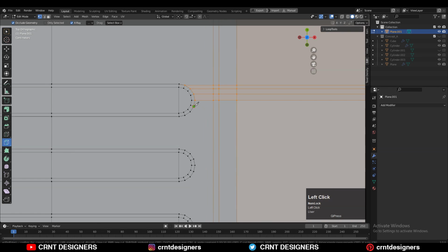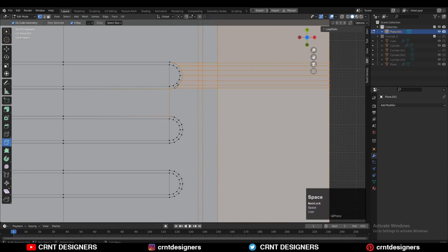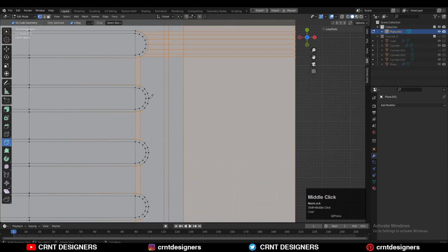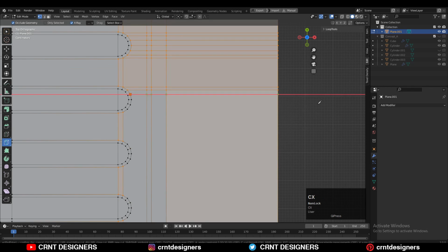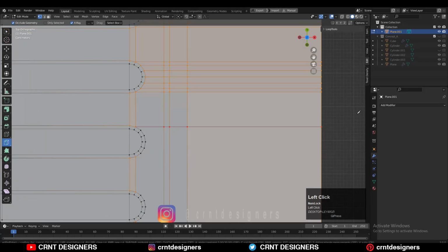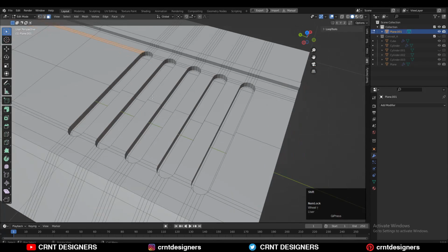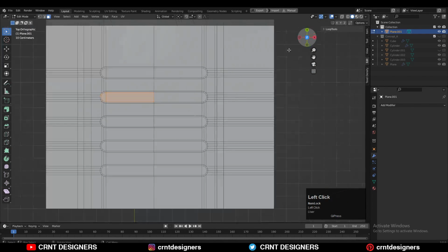And it's not difficult, easily you can create this kind of supportive loop cuts. If you take the less vertex cylinder, it will be better to create the cuts because you need to take a little bit less effort in that case. So you can go with the 8 vertex or 12 vertex cylinder, that's also fine. So you can see I have created the supporting loop structures there for all the boolean details.